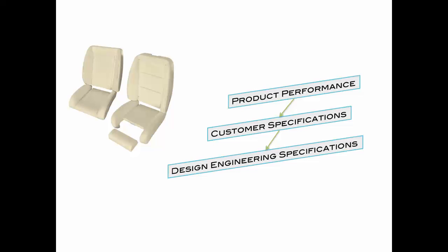seat. So he'll come up with something like, well, in order to be comfortable, the seat needs to be a certain softness. So I need to make it out of foam. So he'll come up with that specification. It needs to be made out of polyurethane foam. Next, he'll assign some kind of durometer hardness to that foam, maybe a 45 in the Shore A durometer hardness